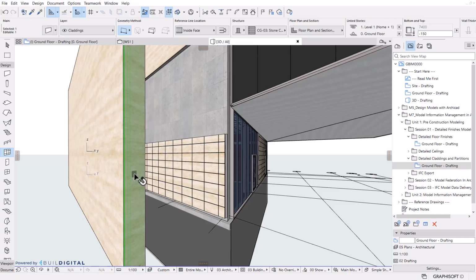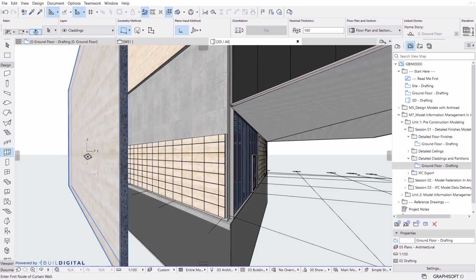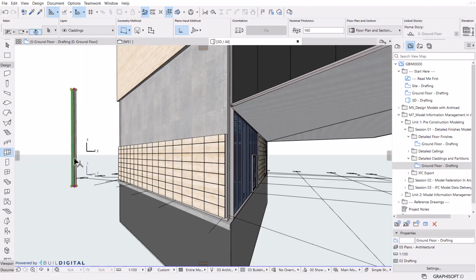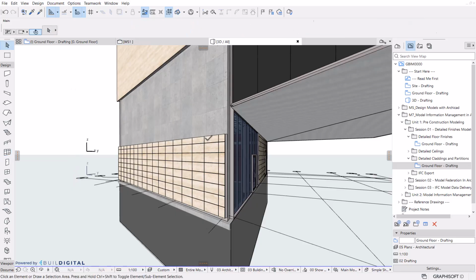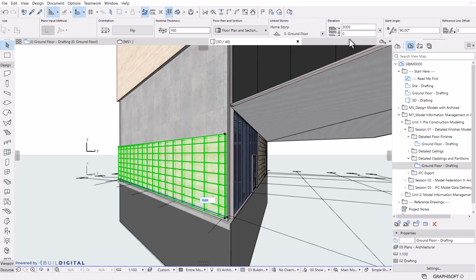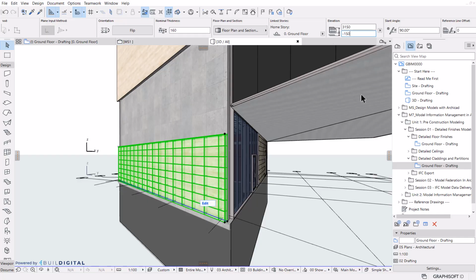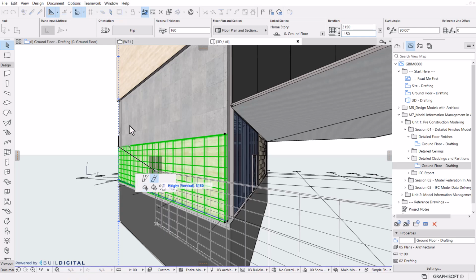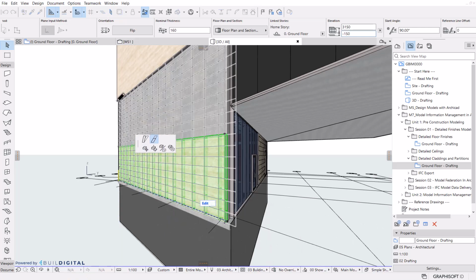Let's delete this wall. We're not going to need this anymore. Like so. And then these can be adjusted in height. Should start at -150. And you can stretch the height with the pet palette option to 7 meters and 500.